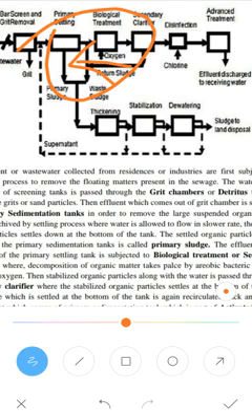This sludge, which has been mixed with the primary sludge, is then subjected to the digestion process. In the digestion process, the sludge is first subjected to thickening, where the amount of solid sludge particles is increased by separating them from the liquid.